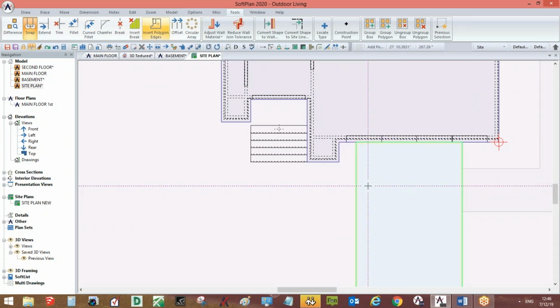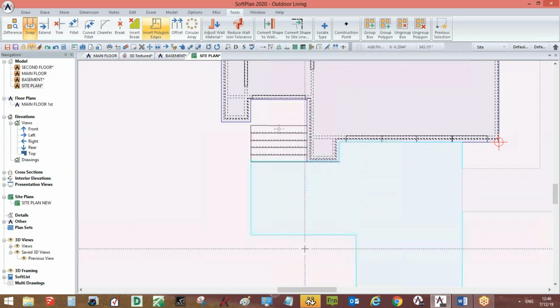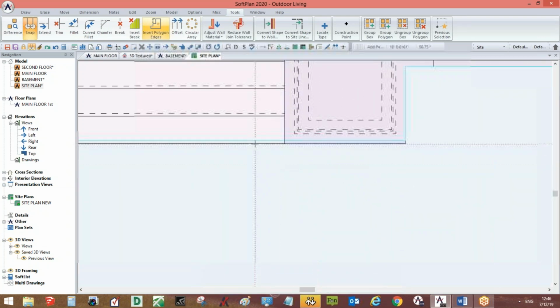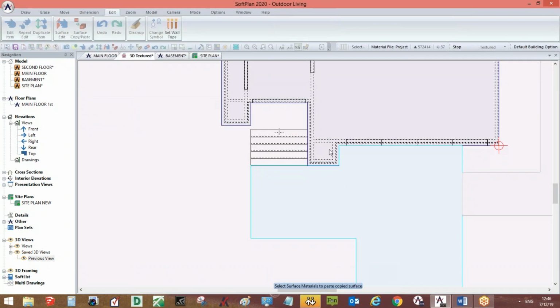So the first click is selecting the polygon, and now we can start tracing those extra edges. It might be easier with cursor snap on for the first click so that you choose the corner you want to start with, and we can turn it off or continue snapping to items. All right, so let's go down and then return to the driveway. Now you can see those extra edges were added. We can adjust it as needed, but we didn't have to redraw the whole driveway.